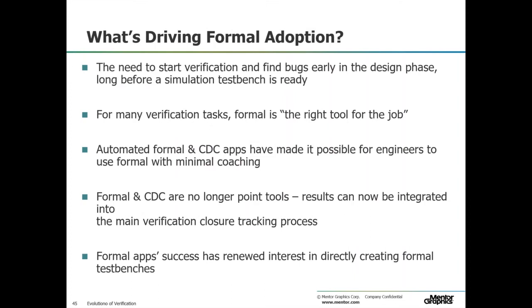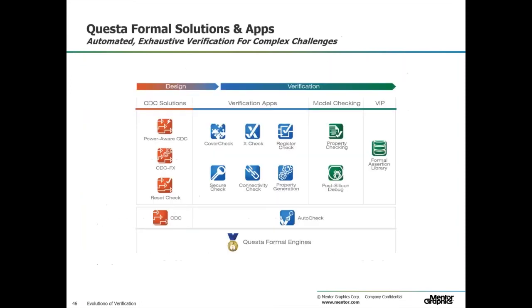I'm not going to go through this whole slide, but basically, there are a lot of hard problems that are not easily solved via simulation, that if you're using a formal engine, it's much easier to tackle, especially things like the clock domain crossing problem. Those are almost impossible to detect in simulation because you really don't have metastability in simulation. They're impossible to solve in the lab because they are very spurious. They don't occur all the time. So CDC turns out to be one of the apps that really works.